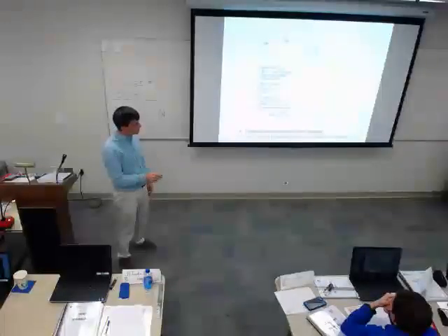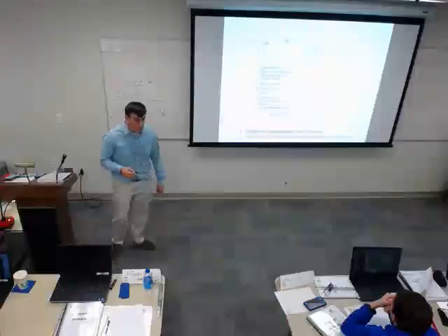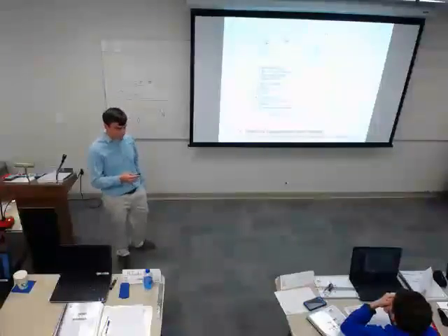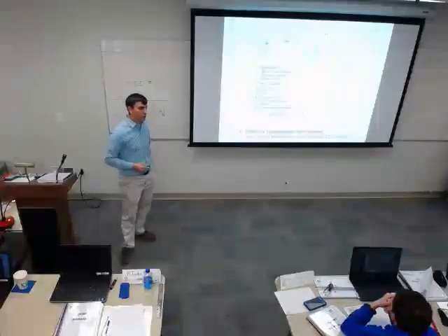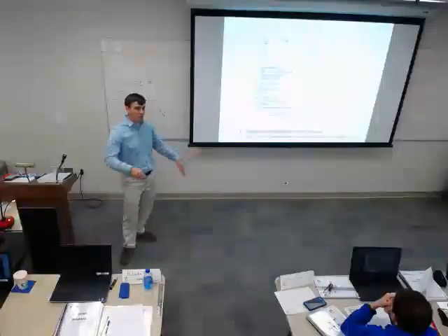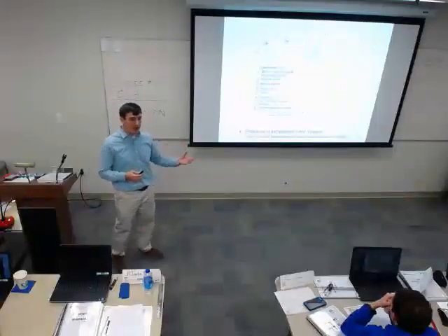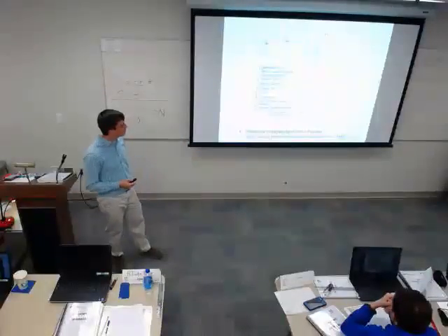If I know I have 0.6 right here, I can calculate what I need to do with this sheave to get 0.75, and then go back and retab everything else. Correct. Everything should be proportional at that point. We're going to talk about proportional balancing as well. Right now, we're still talking about the air handler, pretty much the essential piece of equipment.